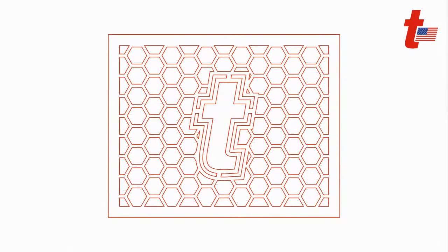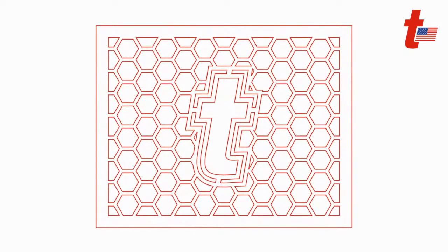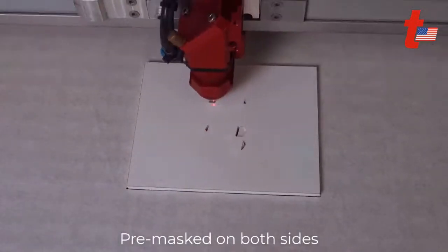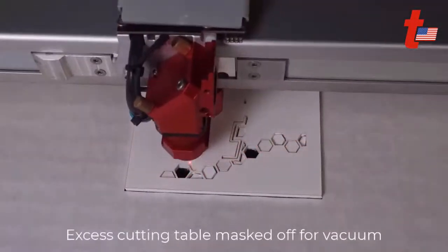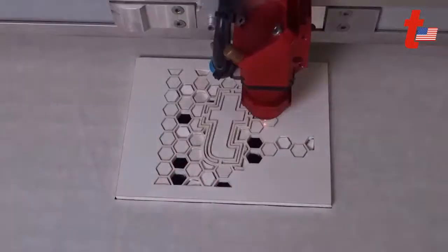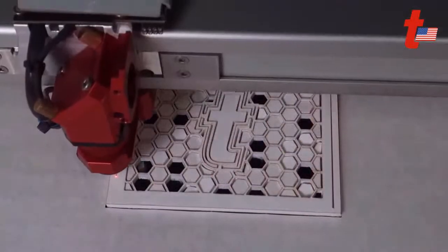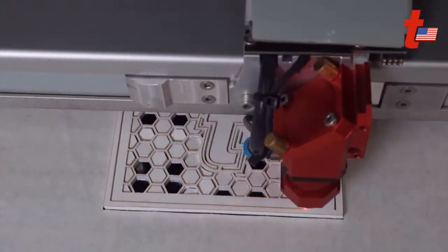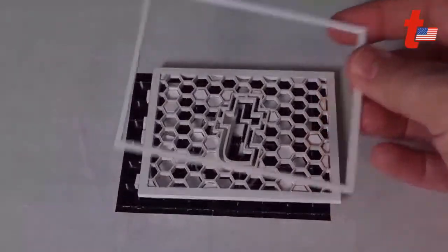Here's an example of a small product that I'm going to actually cut out. This is the one that I showed you at the beginning of the slides for this product. So, pre-mask on both sides. The cutting table is completely covered over except for the location where my part is. Air assist is pushing and cutting through. The exhaust is now pulling through the table, producing a vacuum so that we get that push-pull action. Therefore, we're able to cut through this not very large part with very, very high detail, and then just pop it out of the machine.